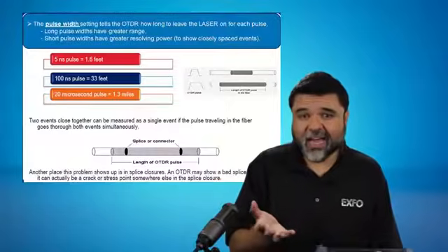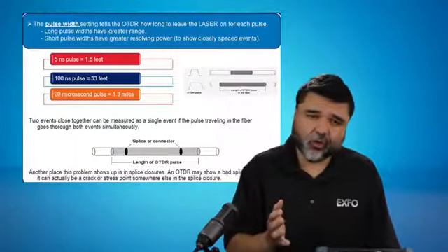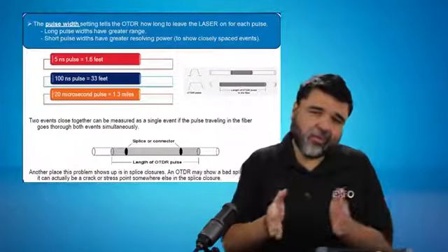So the last thing that I want to talk about as it relates to pulse width is resolution. I've mentioned resolution a few times, but really didn't get into any details. With an OTDR, as you pulse light, the shorter the pulse, the lower the power, so the less distance you'll get, but the better resolution you'll get. So basically how close up the events can be when you measure them. With our OTDR, when you set the pulse width at say 5 nanoseconds, that's about a half a meter pulse. And so you're measuring in half meter increments.